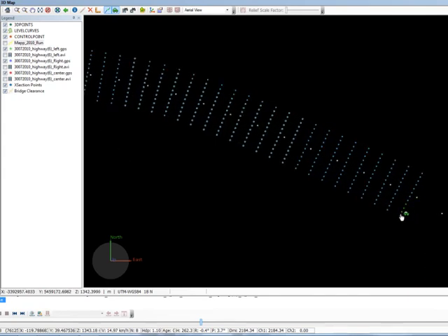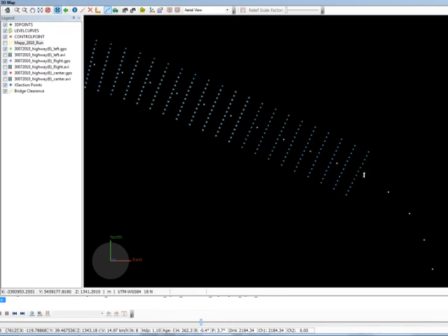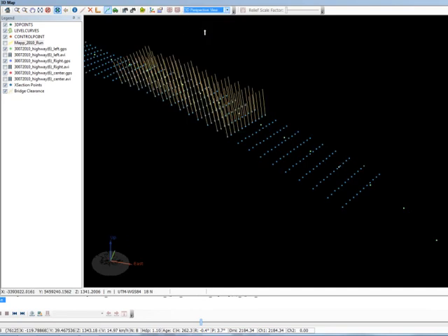For this example, my profiles are 3 meters apart and each contain 12 points. You can recenter the map on a point, select the 3D perspective view to get a better visual of the profile points and bridge clearance.